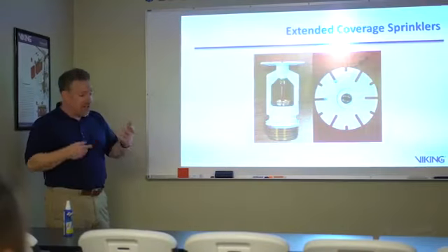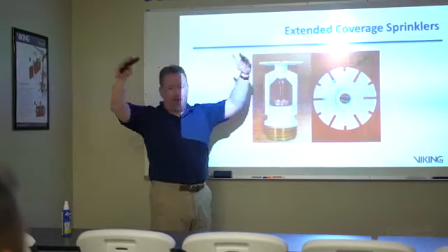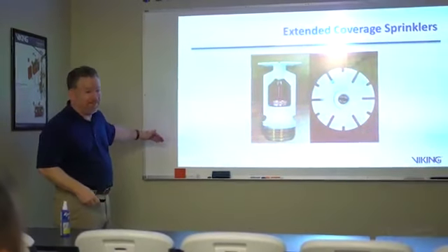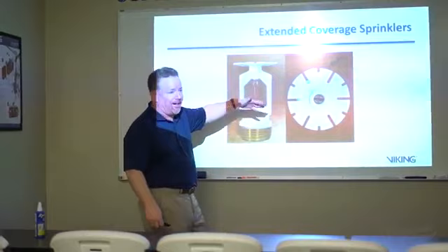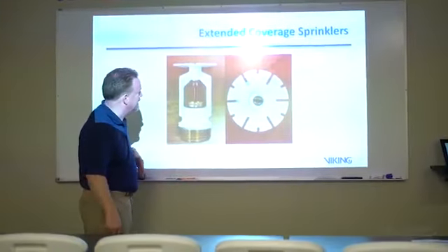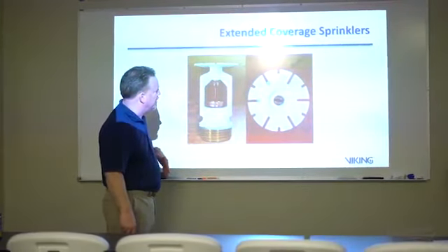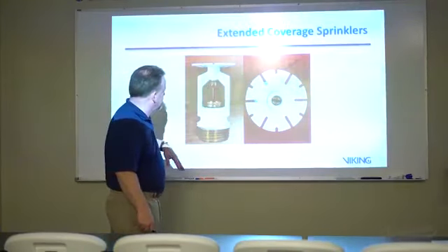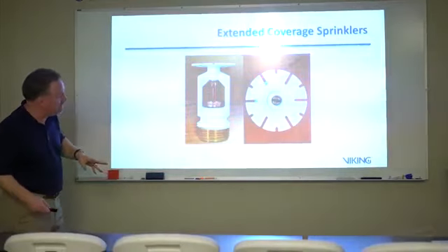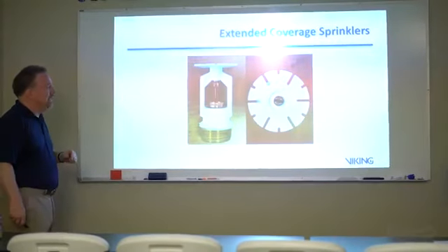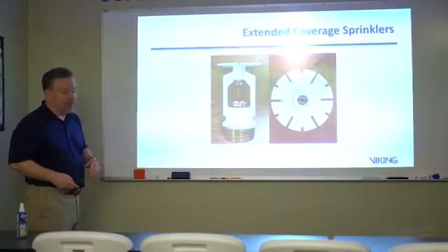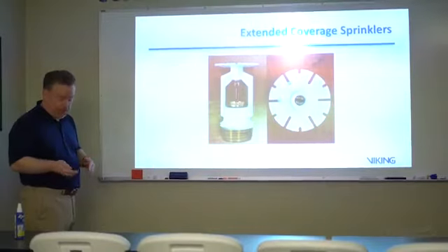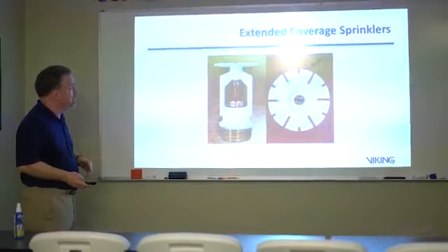Challenges come, obviously, if you're going to cover that large area. Remember the calculation we showed you earlier. You've got to have better pressure, or you've got to have a better, a larger K factor perhaps, to get that further out. So when we start to take a look at this, those are possible, but again, you need to be careful with the design parameters that you're putting in for those sprinklers.